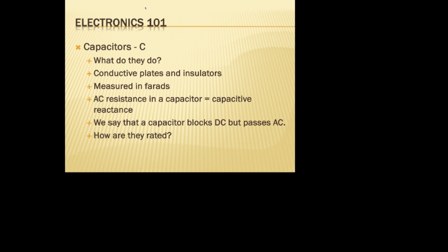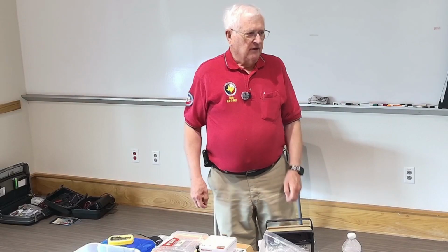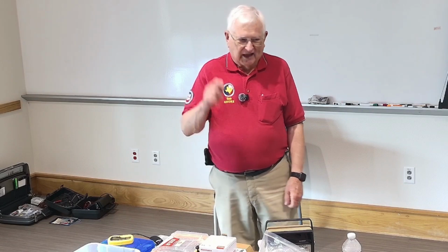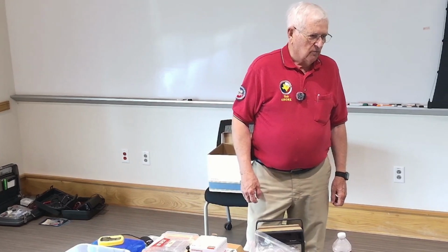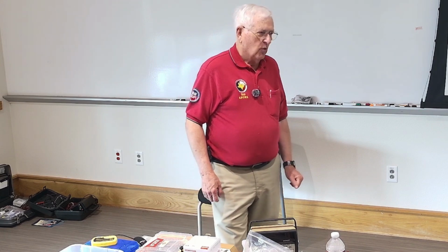Okay, let me get this one on the back row. Those RCL meters that I just passed out, which unfortunately we got one to a row, so you have to play with it and pass it down. Depending on the meter, you hook up the capacitor to the two leads, and then either turn it on, or some you have to select the value, guess at what it's going to be, and tune it in. Others will be a little more automatic than that. So you've got to play with it and figure out what the meter wants. It should give you a crude guesstimate of the capacitance of any of those capacitors that you have as samples. That's the whole point behind it.